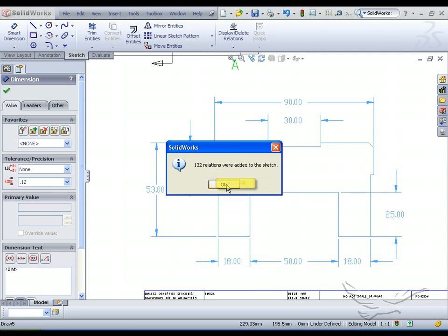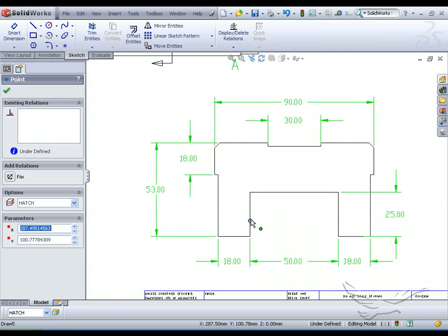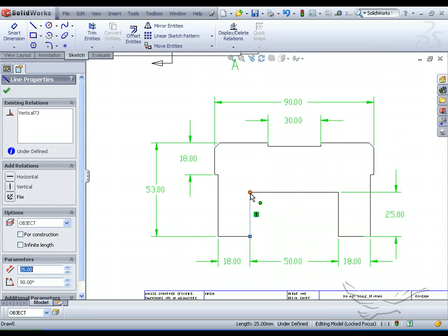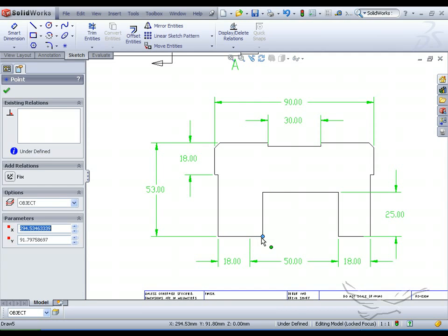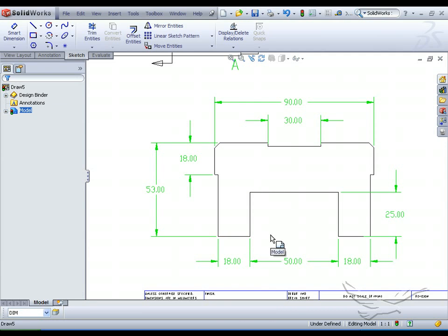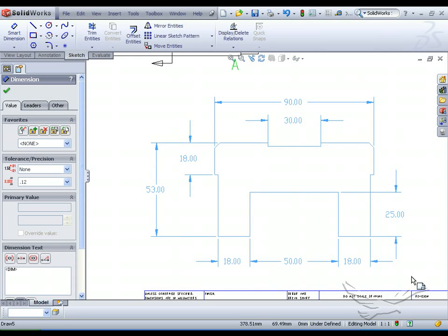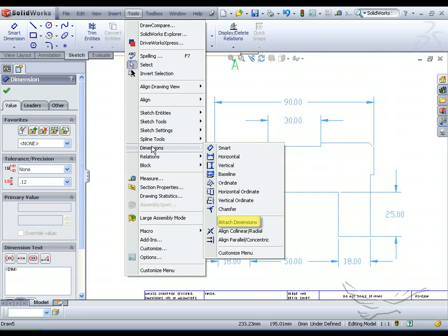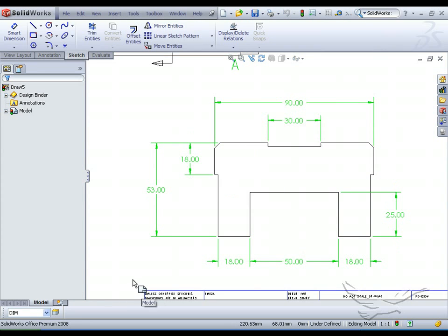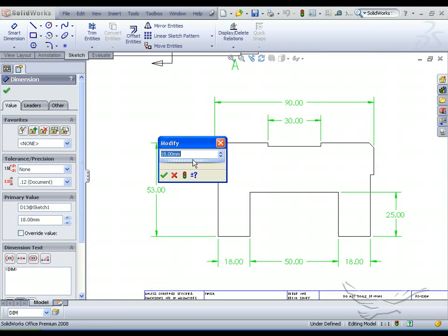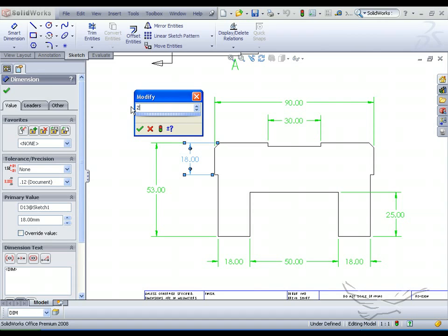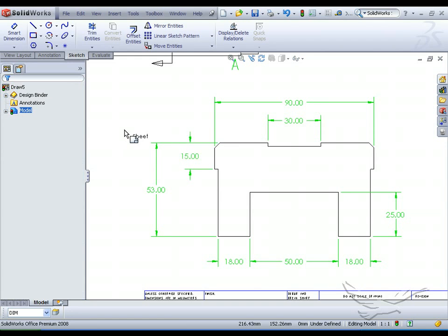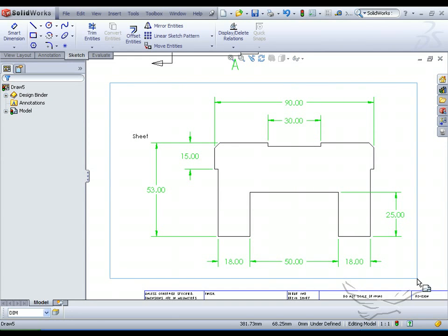Now, I want to box select the view and from the Tools pull-down, choose to constrain all the relations. Now when I move the geometry, it will keep the orientation to the original import as compared to the surrounding geometry. I'm going to select the items again and go to the Tools pull-down to attach the original dimensional values to the geometry. This will make the dimensions driving parametric values. This means a dimensional change will rebuild the geometry automatically. Notice the line on the other side remains collinear due to the relations added to the geometry earlier.